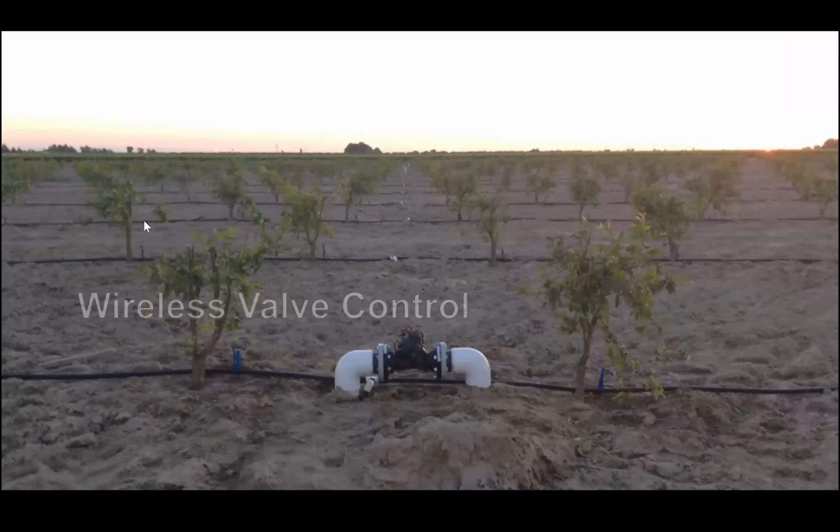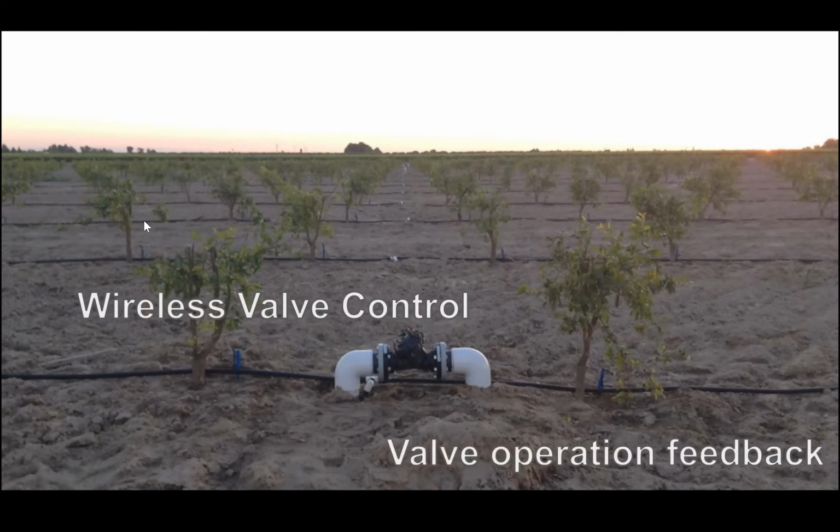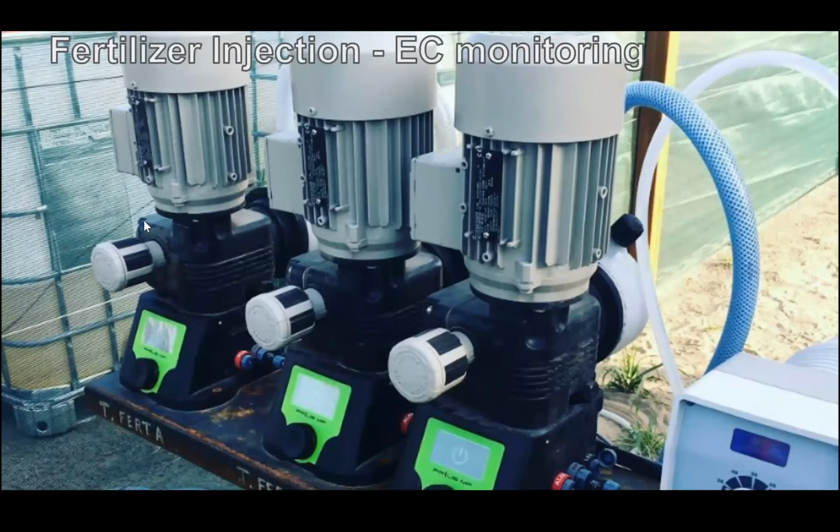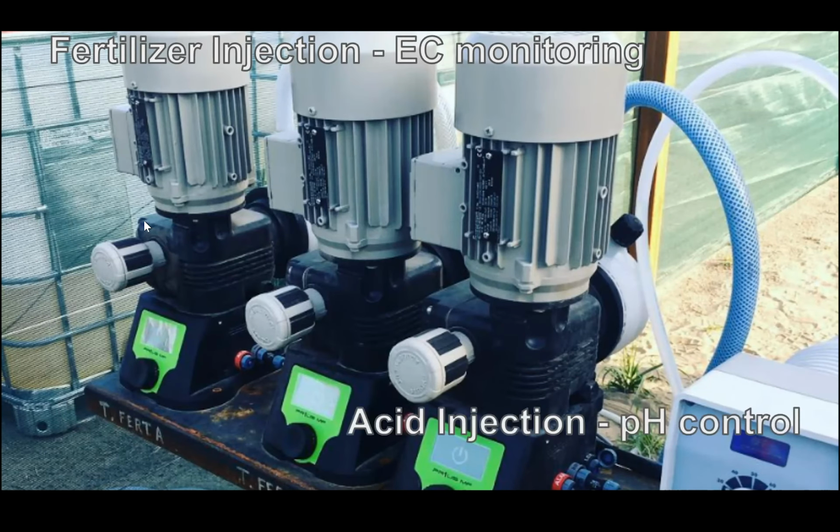And then in the field, we open and close the valves, hydraulic valves operated through solenoids, and we deploy sensors, usually pressure switches or pressure transducers that will give us feedback of the valve operation. We are also involved in the fertilizer injection, monitoring electric conductivity and fertilizer injection, controlling the pumps that inject the fertilizer from the tanks, and acid injection in case you're using this for pH control that can also be tied into a pH sensor on the pipe and run a control cycle in order to maintain a pH on the water.